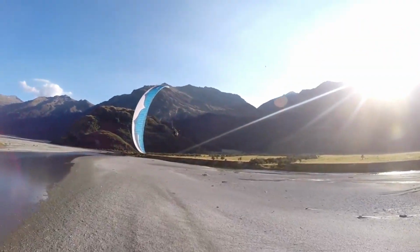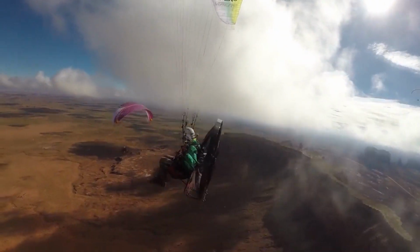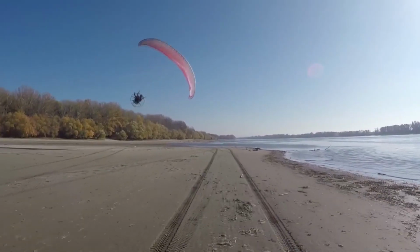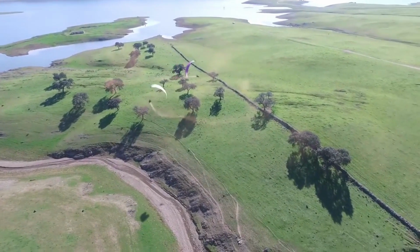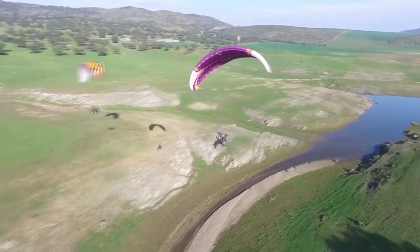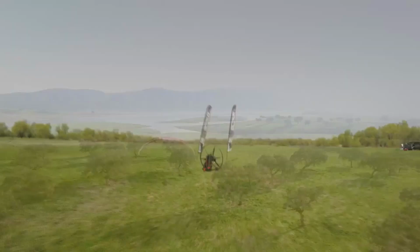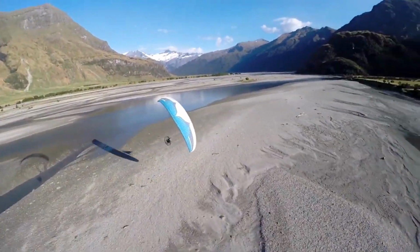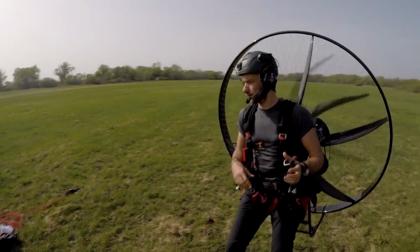The torque reaction does have a noticeable effect on the WSC aircraft. With the typical left-hand turn tendency, for right-hand turning propellers, turns are not typically built into the wing. As in airplanes, some cart designs point the engine down and to the right. Others do not make any adjustment, and the pilot accounts for the turning effect through pilot input. It should be noted that many of the two-stroke propellers turn to the right, as do conventional airplanes. However, many four-stroke engine propellers turn to the left, creating a right-hand turn. Consult the POH for the torque characteristics of your specific aircraft.